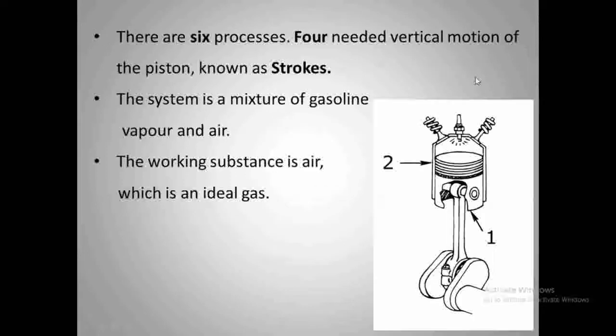If the piston is receding, the fuel, which is in the form of vapor, and the air can come into the chamber. Because the pressure inside is initially 0, and the atmospheric pressure is P0, that pressure can push the gas and vapor inside the chamber if the valve is open.